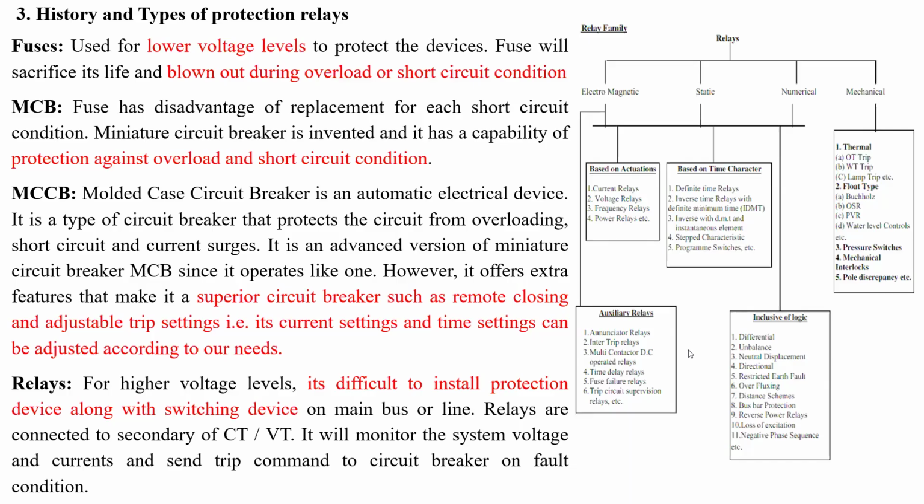That is, current settings and time settings can be adjusted according to our needs. As it is equipped with motors, we can operate the motor mechanism from a remote end also, using the SCADA system or the PLC system, to close and open this MCCB whenever required.